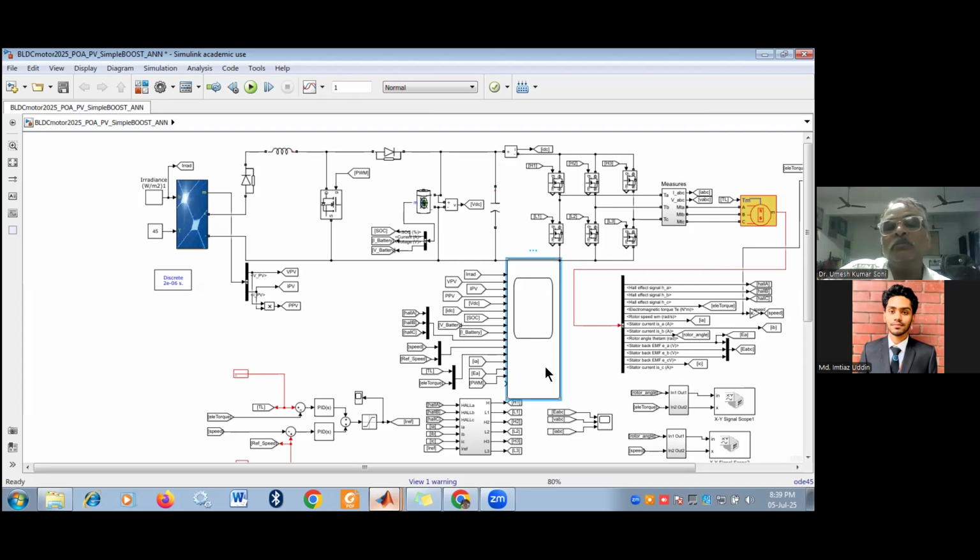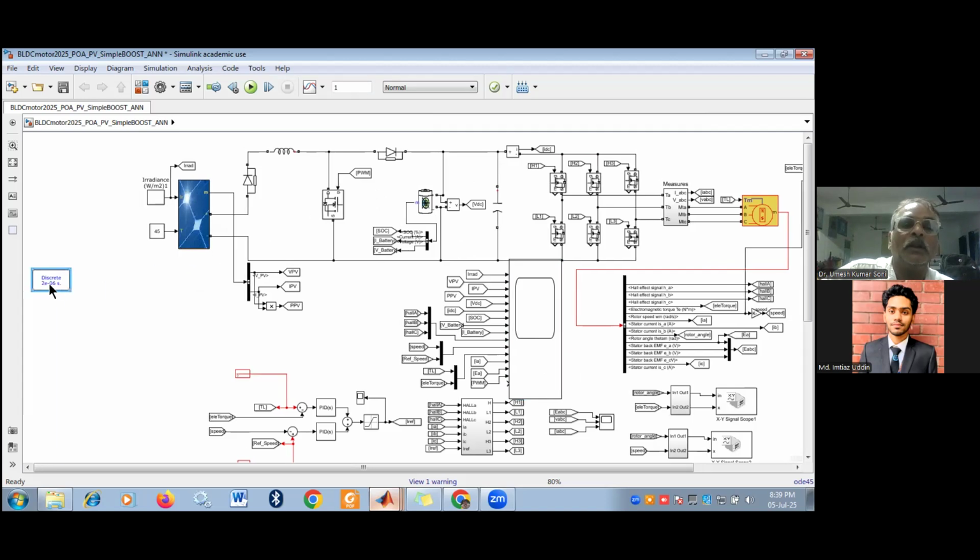So in on-grid mode we do not need the storage system. In off-grid mode we need the storage system so that we can store the energy for future use. During lower loads the SOC will increase, and during heavy loads and lower irradiance or energy generation, there will be a higher SOC drop and the voltage will be lower.